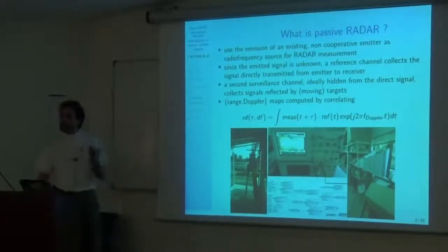And so what is your estimator? What is the signal processing you need to run? Well, you're looking at a reference signal. This reference signal might be Doppler shifted, and it will be time delayed on your measurement channel. So your correlation, what you're looking at is, can I find the reference signal in time delayed copies of a measurement? So that's the tau here, the time delay.